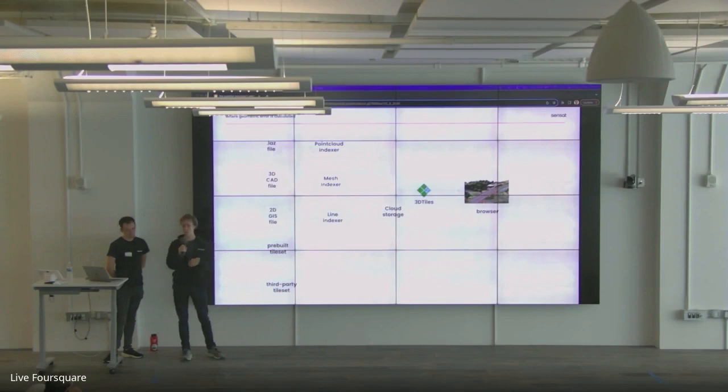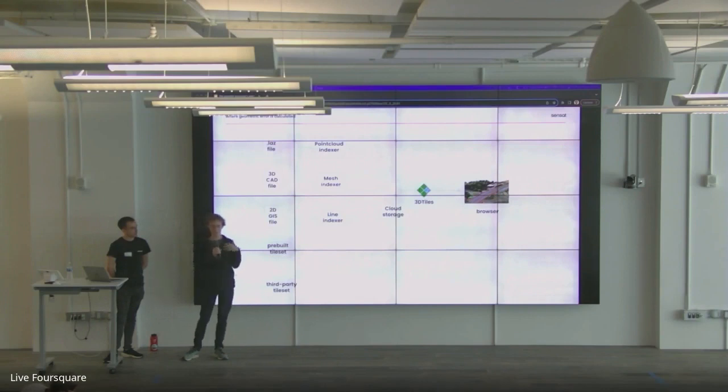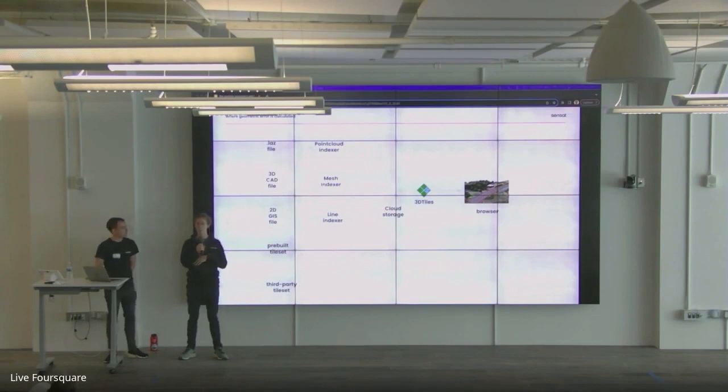And what we found in practice is that different renderers, as much as we would like, and I think the spec would like, for renderers to be agnostic to the source of a tile set, so that as long as it conforms to the 3D Tiles spec it doesn't matter which renderer you're using, it should just work. What we found in practice is that the tile set structure, like how large the tiles are, how deep the tile set is, whether you have lots and lots of small tiles or a smaller number of larger tiles, can affect rendering quality in different renderers.